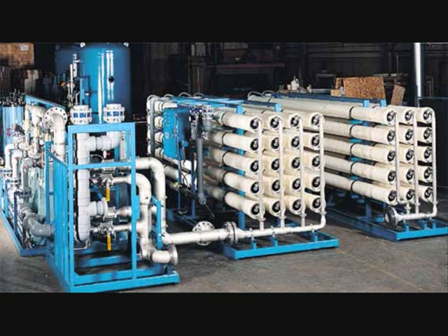The most frequently used form of desalination is reverse osmosis, and that's the image that you see here. These are simply filters that allow water through but do not allow the salt, the sodium and chloride ions, through. They are too big to pass, and that water is pumped under high pressure through these membranes. On the one side it's saline, on the other side it's fresh.